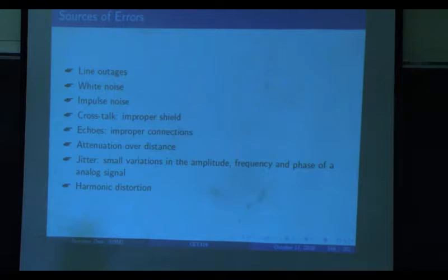So k, the Boltzmann constant, times T, the temperature, times B, the bandwidth. The larger the bandwidth, the larger the thermal noise. The higher the temperature, the higher the noise. It's proportional to temperature and bandwidth. The temperature needs to use the unit Kelvin.